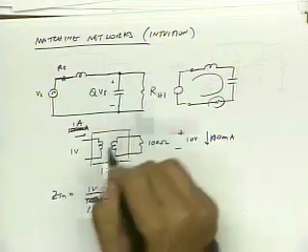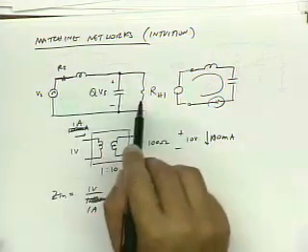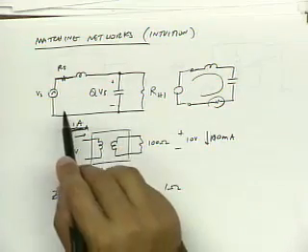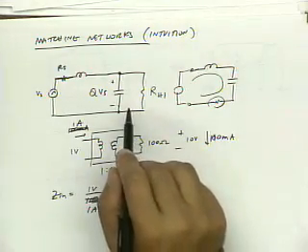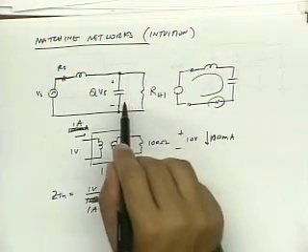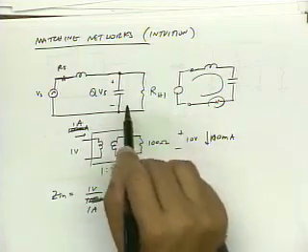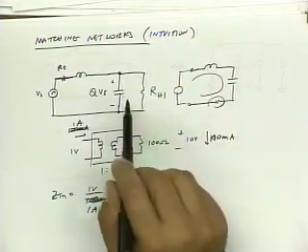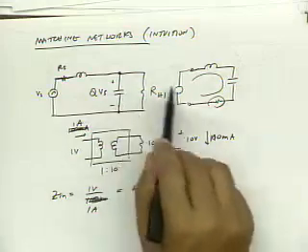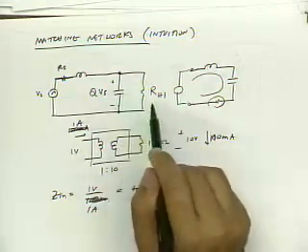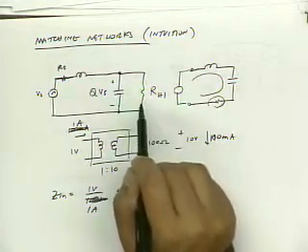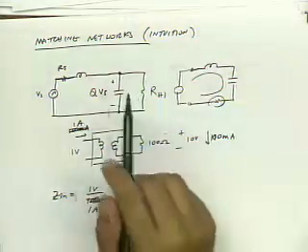And that means that because I have a voltage multiplication, I have the same current multiplication in the other direction. So the current that I can drive this with is 1 over Q times smaller. So the net effect is that I've decreased this by a factor of Q squared. I think I'm getting things wrong here.